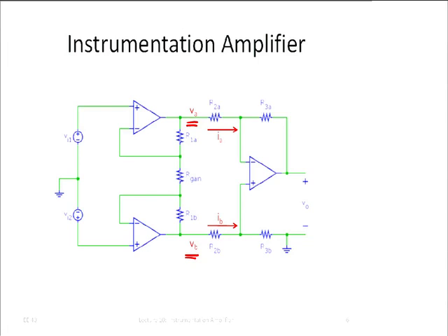Right? All what you said was correct, but the insightful answer that I wanted now is that the output resistance looking back into the amplifier is 0. That means the voltage doesn't depend at all on how much current I pull out of that output of the amplifier. And now, if it doesn't matter how much current is flowing out, well then, I also could analyze the circuit, for example, for a current of IA equals 0 and IB equals 0.